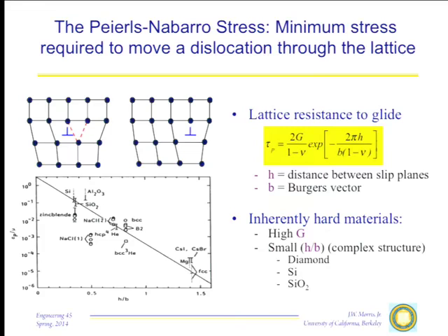The advantage in these materials, as I said last time, and I will re-emphasize, is that they are very interesting because they can have true elastic behavior over a very wide range. So if you want, for example, to make a spring that will not undergo transient deformations when you use it, you use these materials. Any other thing where you want to be sure that your behavior is purely elastic, under significant stresses, you want to use these kinds of materials.